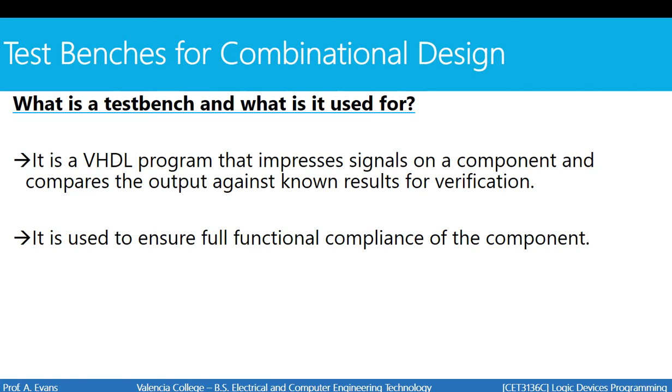So part of the process for developing a component is to write a test bench for that component. The purpose of the test bench is to verify that that component does work as indicated. So for example, we're going to look at the code for a half adder, and we're going to write a test bench to verify that our code works. We use a test bench in conjunction with functional simulation and real-life testing on the breadboard to make sure that the component works as designed for every possible set of input combinations.